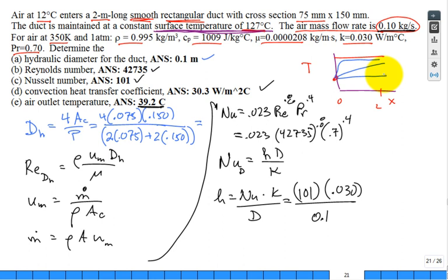There's a whole range of conditions. But we probably want to use that exponential equation for the theta that we derived. What was that equation? So the theta at x equal to L is equal to the theta initial coming in, e to the minus, then what do we have here? hPL. I'm really botching that, aren't I? Get rid of this 0.1, 0.1. Okay. hPL divided by m dot c.